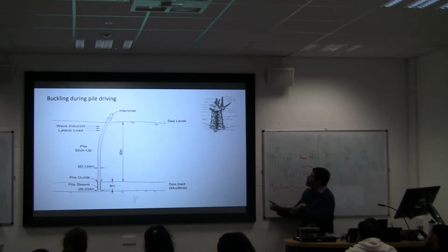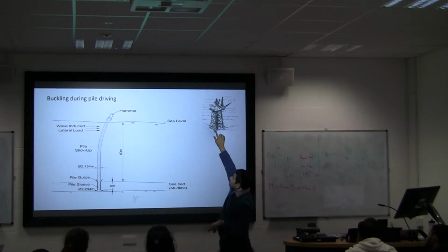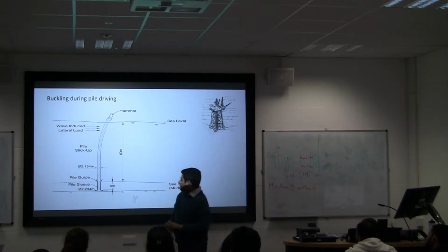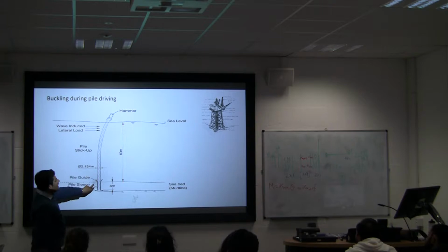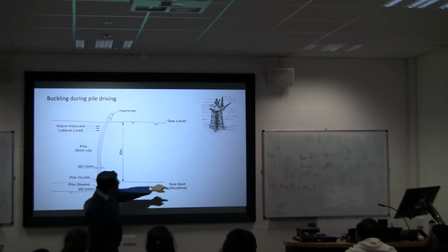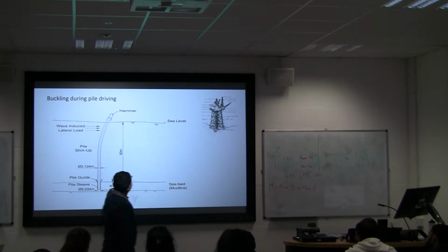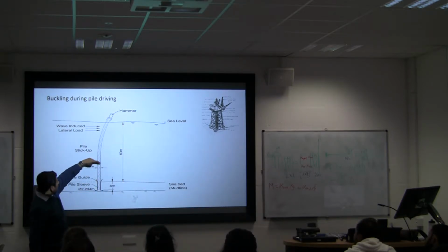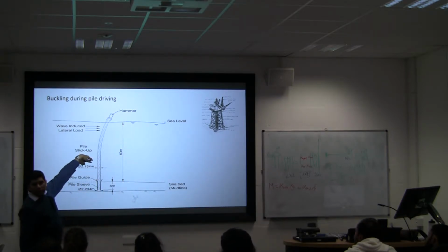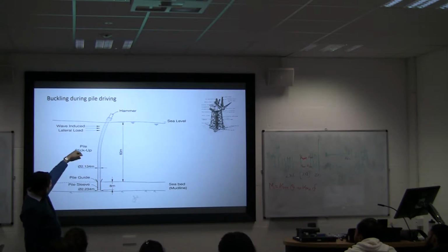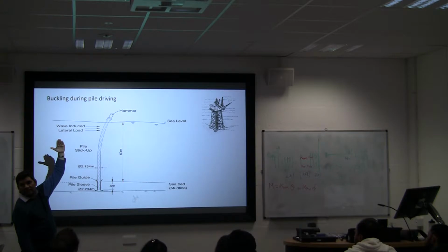So if you see, that's the sleeve here. You can see the sleeve. You put down the pile there and you drive from the top with a hammer, right? And the sleeves are typically 8 meters in length.